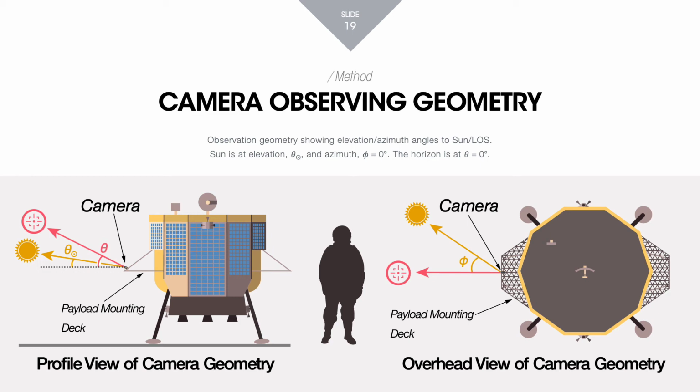The model abundances can be combined with the radiative transfer forward model and dust scattering grid and used to generate the radiances that will be observed by a notional camera. We can now compare these radiances to the detection limits of a nominal dust monitoring camera in the presence of other background sources, for instance zodiacal light, in order to assess its capability as a dust monitoring instrument. The camera sensitivity model was created from commonly available wide-angle optics and COTS image sensors with flight heritage.